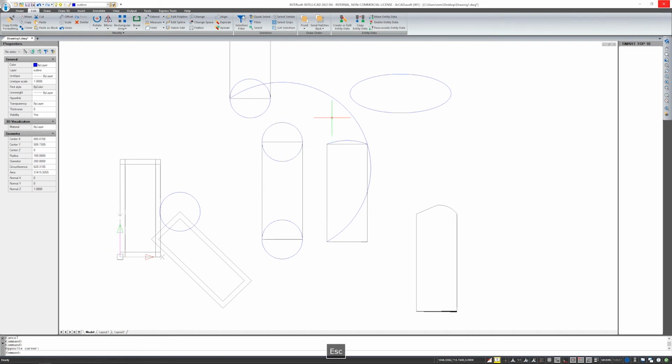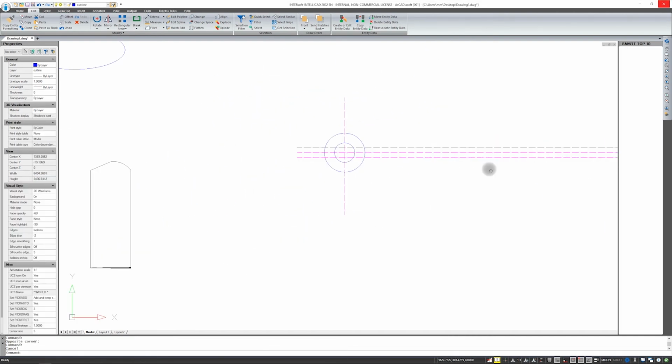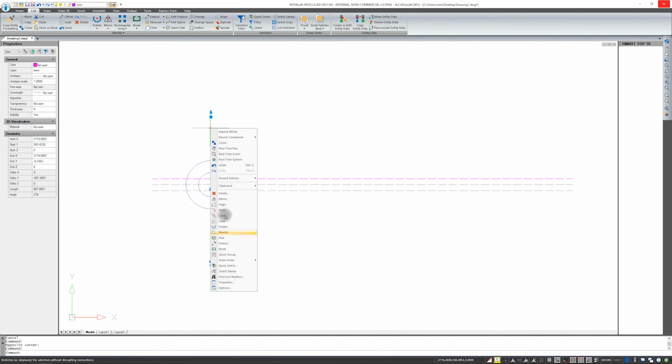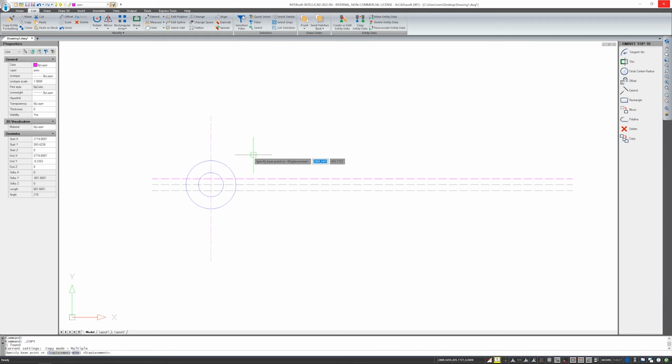Now I will show you another example of copying. Select again, right-clicking, and then Copy options. Now you can choose the displacement option you have here under the cursor in the angle brackets. And if you press the down arrow, you can choose the displacement and say how long this copy of yours should be, right or left, up or down. I would like it to be between these axes, so that there will be 650 units.